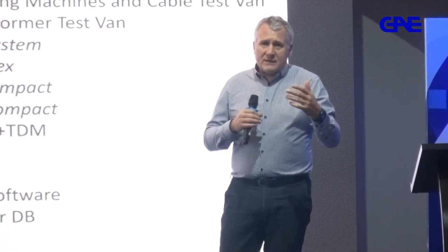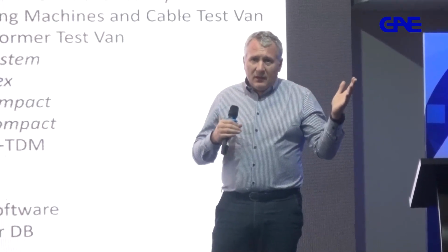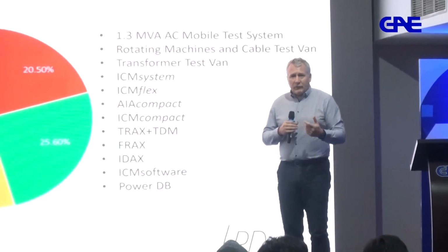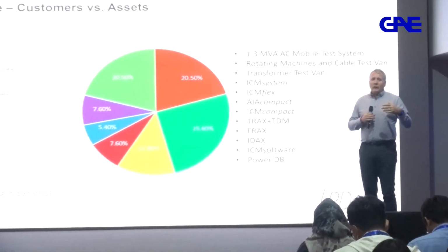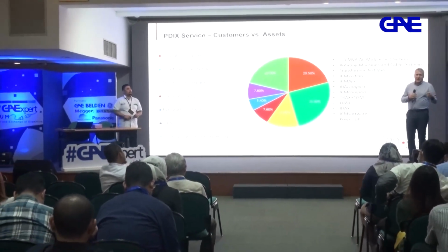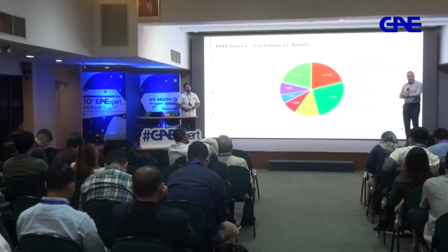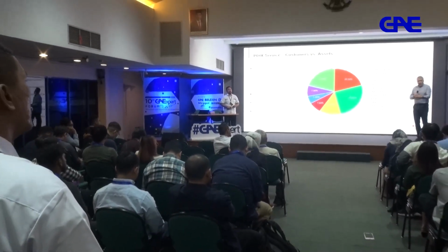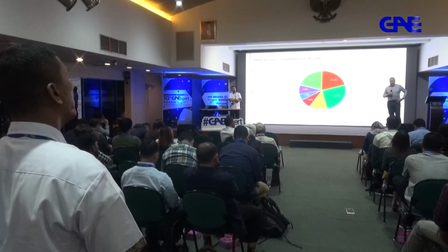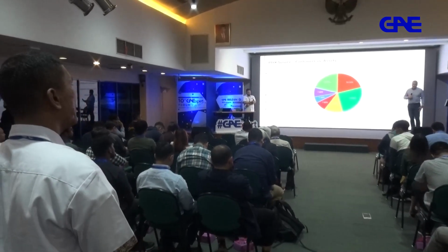So that's why, for instance, some of these tests are done in special test rooms, Faraday cages, especially in production, because people want to not be subjected to this noise. But once you go in the field, that's the place where it's very important to understand where you're going to place sensors. Sometimes, where do you place gating sensors? Because we have special corona suppression antennas, and we have high frequency current transformers that you put on the ground plane. So you need to use those many times to suppress noise, to gate noise. Those are the methodologies usually used.